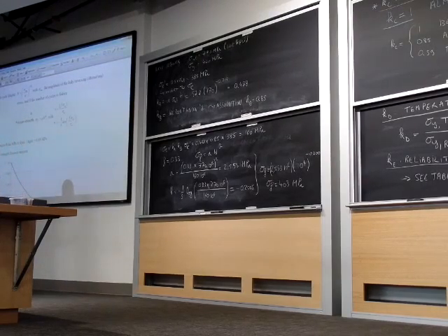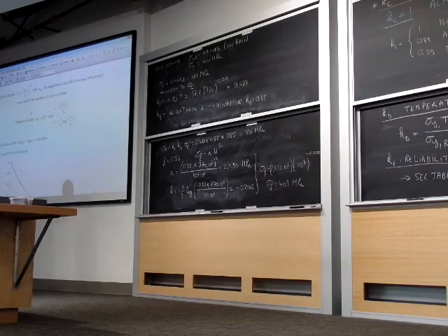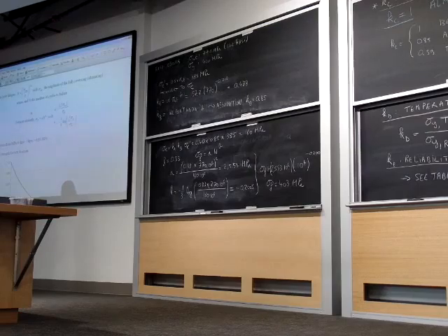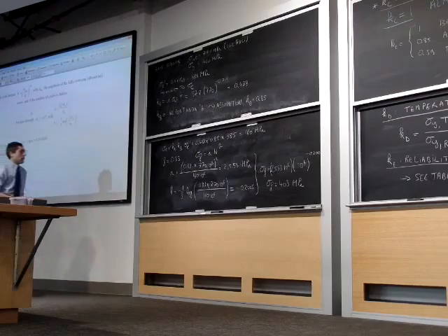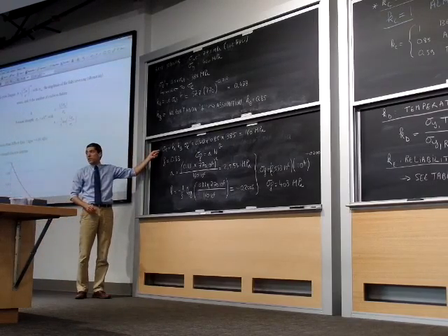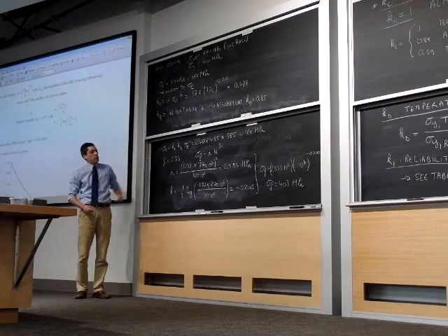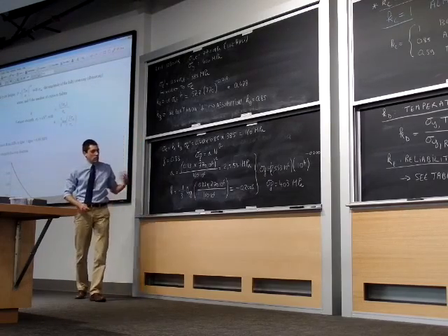When we get our result, even if it's an intermediate result, we do our little sanity check here. We're expecting this to be somewhere between sigma ut and sigma E, right? Sigma E would be for infinite fatigue life, the stress amplitude that gives you infinite fatigue life. We don't need to reach infinite fatigue life, so you expect that the fatigue strength is greater than your endurance limit, which is the case, right? So we got 403, which is significantly larger than 160, because 10 to the power 4 cycles is a long distance away from infinite fatigue line, right? So that seems to make sense. And it is smaller than our ultimate tensile strength. That seems to make sense too.